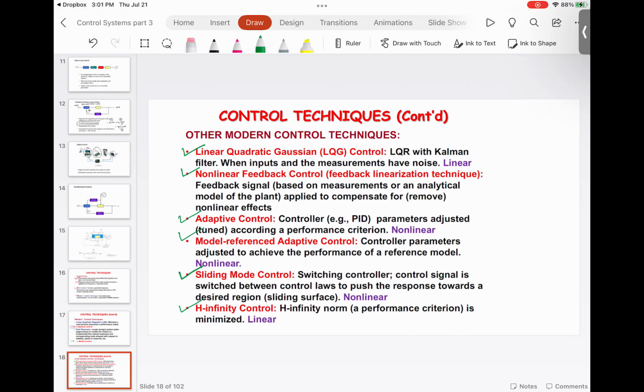And I just want to give you a quick note here that all these control laws can be implemented on TC Lab. So we are going to start TC Lab with a simple bang-bang and PID control. Bang-bang control is turn on and turn off and see the performance. PID control is add the proportional, derivative, and integral terms and then make the control behave the way we want.